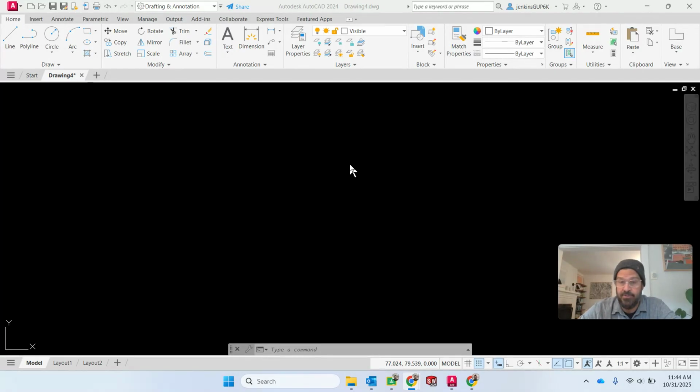One thing to make clear right at the beginning is that as our drawings become more and more complex, you're going to want to use what are called different layers. A layer is like, if you imagine a drawing and then you overlay some kind of very clear, thin piece of plastic in front of it, so you can annotate your drawings, you can make multiple layers. AutoCAD works in the same way. You can have multiple layers of a drawing, turn layers on or off, or move one layer forward or backwards. You can control where you're drawing.